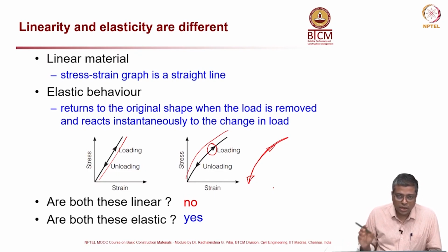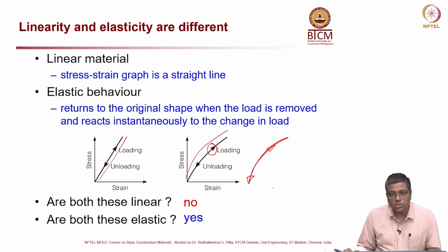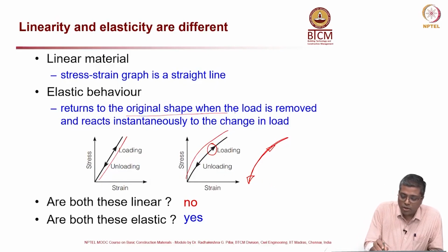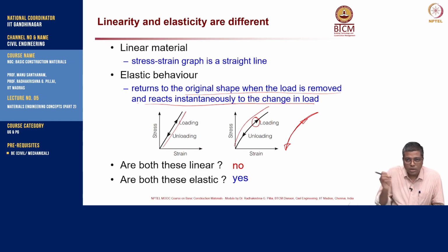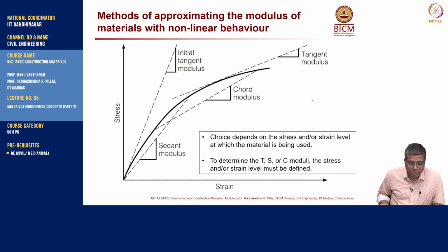So, in case of elastic behavior, it returns to the original shape when the load is removed and reacts instantaneously to the change in load. Instantaneously means the moment you release the load, it reacts immediately. There is no time lag. Okay. If there is a time lag, then we call it viscoelastic behavior. We will talk about that later. So, here it is elastic behavior.